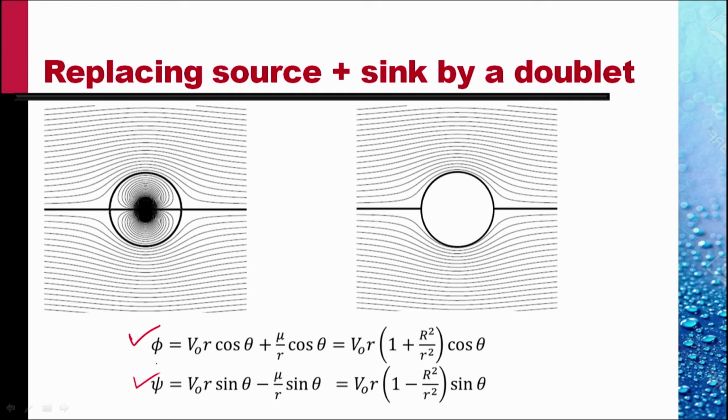We had also calculated the velocity distribution on the surface of the cylinder, and using this velocity profile, we had calculated the pressure distribution using the Bernoulli equation. If the flow did not separate over this cylindrical surface, then that is exactly the pressure distribution that we will get, or that is approximately the pressure distribution that we will get.